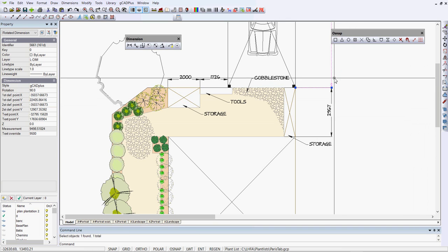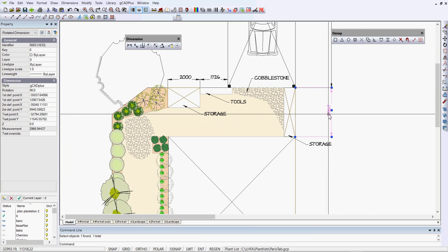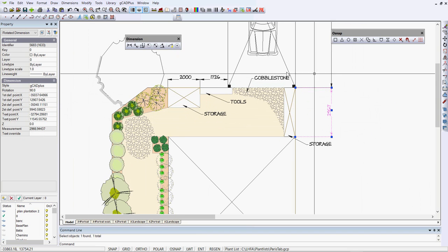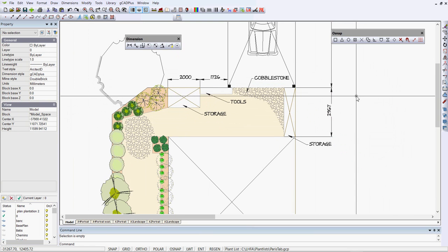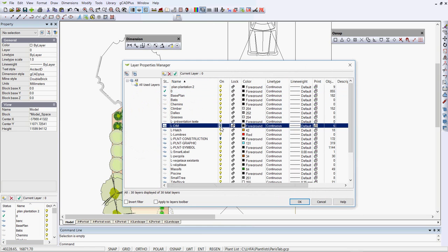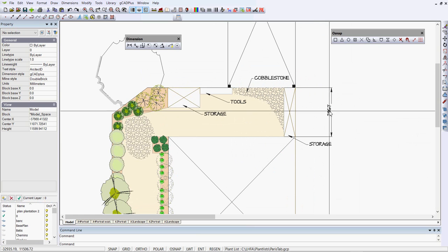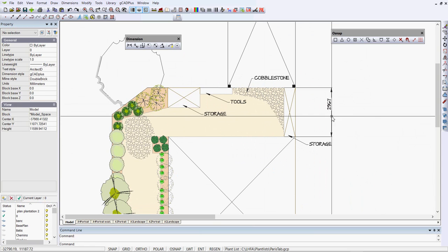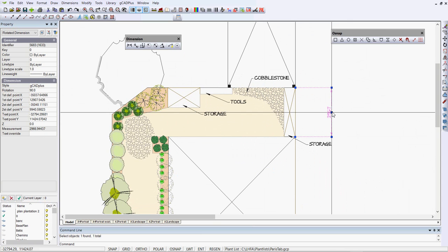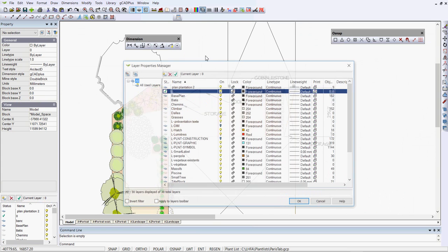We recommend putting all dimensions on a layer called LDIM, that one that I just put on, because layer 0 was current, has gone on layer 0. What that means, if I go to layer here and I turn off the dimensioning layer by clicking on that light bulb, everything disappears except that one. I'll undo that. Sorry, it didn't undo my settings for my layer.